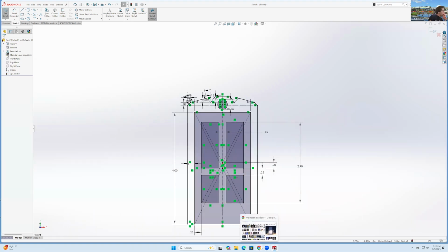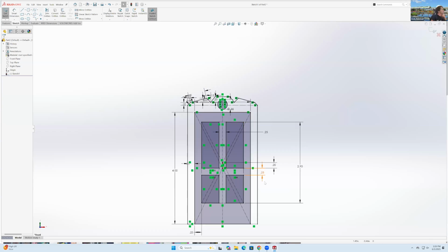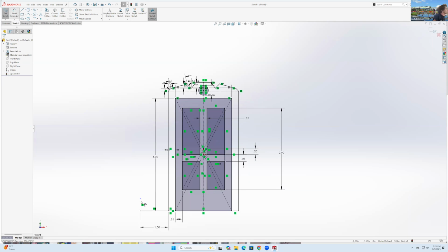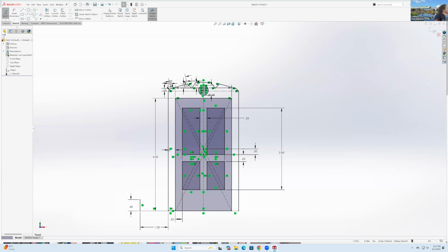So now let's go back to our original picture and draw these things that go out there, at least the outline of them. One way to do that would be by using a spline. So first I'll say that I want them to go more or less this far. So I'll do a smart dimension of this, maybe up to 1 inch right there. Yes, and I'll mirror all of this afterwards. We're gonna call this the advanced model. We're not gonna make it identical, but